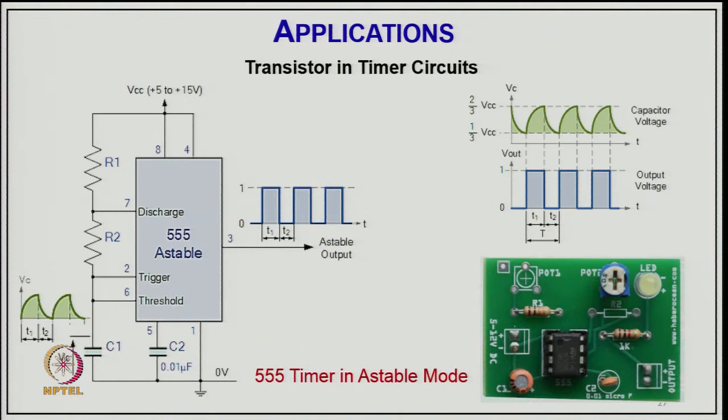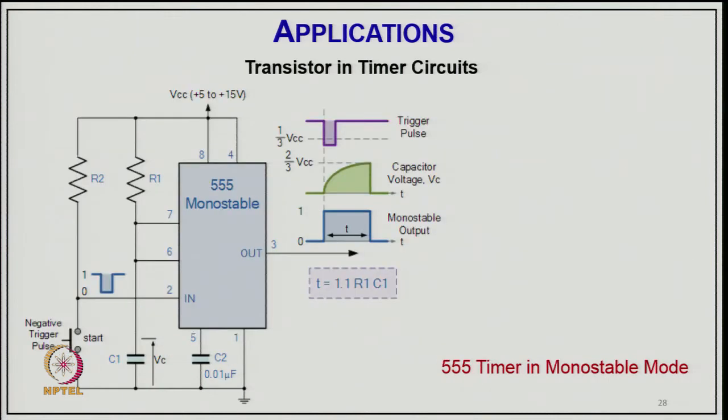And from this chip you can design an astable multivibrator, and you can decide how much the duration or frequency should be. This is the internal structure of it. You have to put external components connected between the different pins to decide the frequency and duration of the pulses. This is the typical complete circuit of your 555 timer chip, which you are using in astable mode as an astable multivibrator, using a single chip.